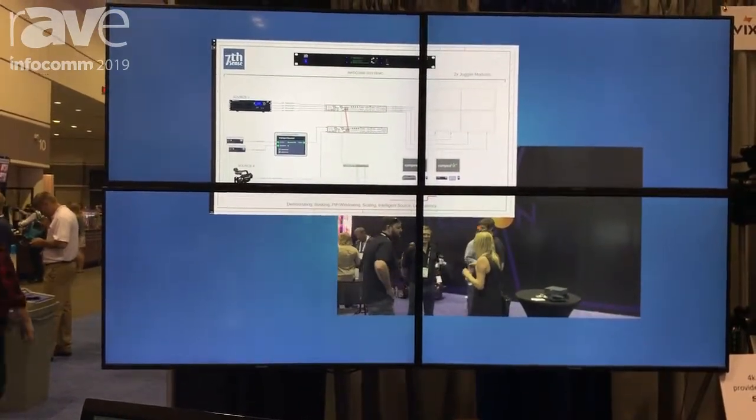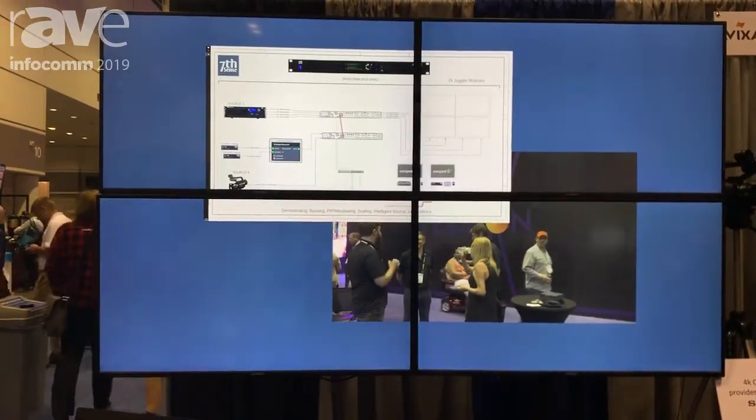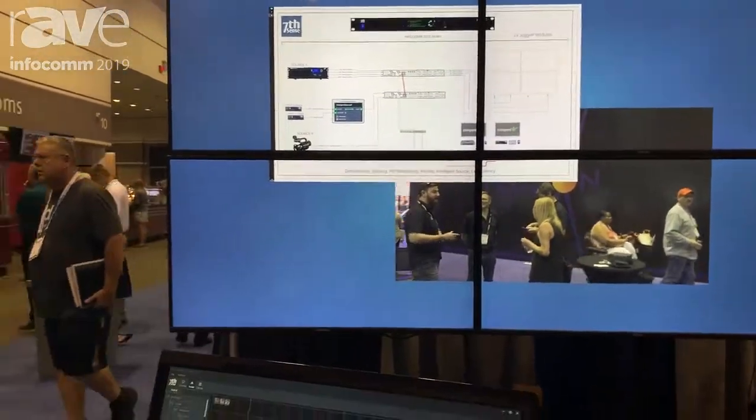Since it's an FPGA product, that code could be placed right in the first several pixels of the image, so we can detect the problem and act on it or warn on it even if we haven't brought in the entire frame. Before the frame even finishes drawing, we could be switched to a plan B source, a canned playback or a B bank of render engines, something like that. So that's what the Juggler's about.